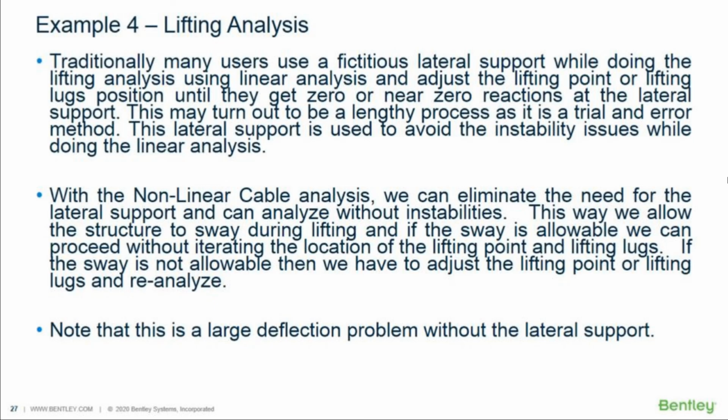With the nonlinear cable analysis, we can eliminate the need for the artificial fictitious lateral support and analyze without instabilities. This way, we allow the structure to sway during lifting, and if the sway is allowable, we can proceed without iterating the location of the lifting point and lifting lugs. If the sway is not allowable, then we have to adjust the lifting point or lifting lugs and reanalyze.